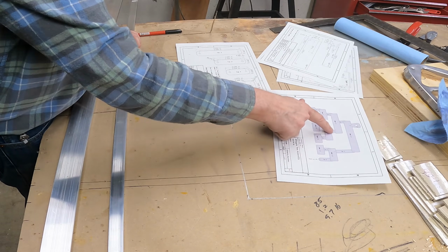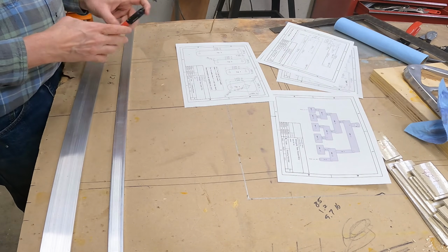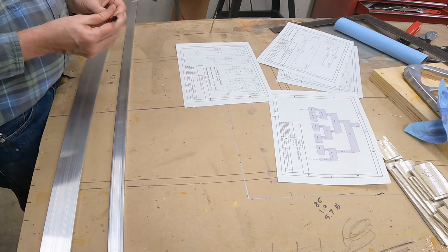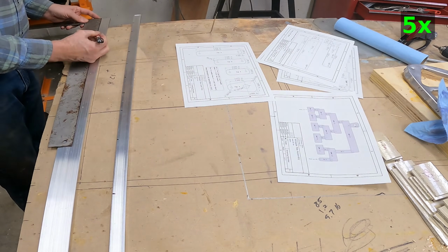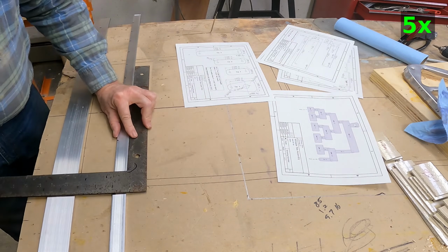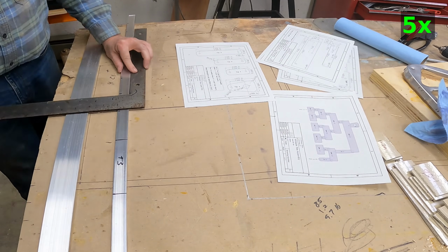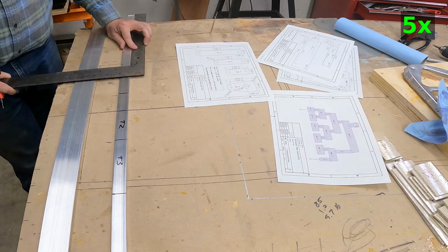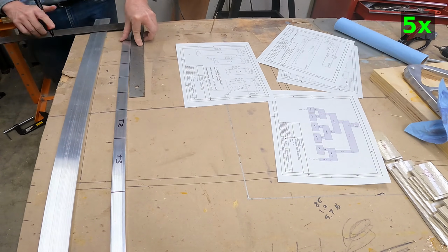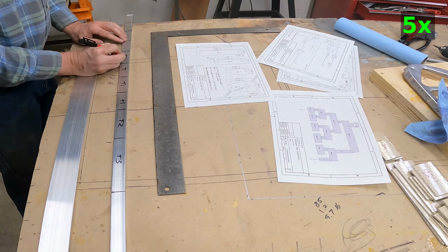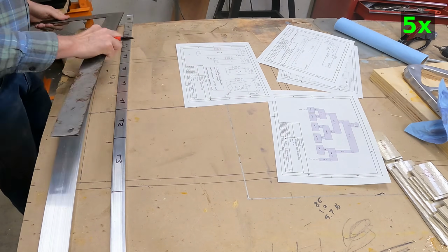Well, next I made the vertical ties to tie one tier of load spreaders to the next upper tier. Now most of these ties only go one tier. I wanted the load spreaders to be 100 thousandths thick, but I wanted these vertical ties to be 125 thousandths thick, and I didn't have any of that, so I had to go buy some rectangular stock. So almost all the vertical ties are 1 inch wide stock, except for the very top one.